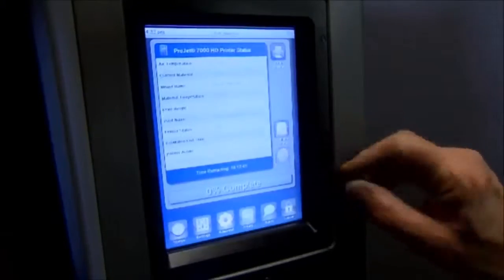Stereolithography is a 3D printing technology that uses photopolymerization, a process where light causes molecules to link, forming polymers. It is one of the oldest 3D printing technologies, originating in 1983. A layer of photosensitive liquid is exposed to a UV laser beam, forming the pattern as it begins to harden.